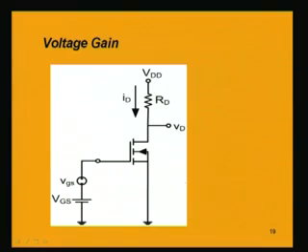What will be the voltage gain when we are giving an input small vgs? This is the input, given at the gate to source terminal. This is the drain terminal, this is the gate terminal, and the source is grounded. This capital VGS and capital VDD are there, which are required for biasing, because we know it is an enhancement type N channel Mosfet.